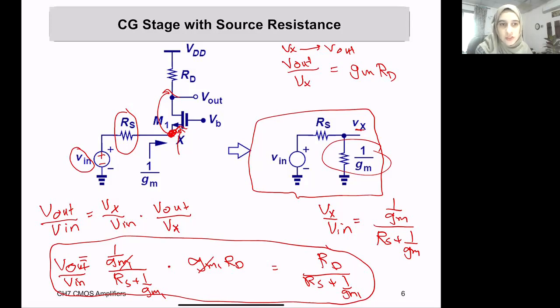I mean, now what has changed? There is an addition of this resistor Rs. So not entirely the Vn is reaching the Vx node. From this node to this node, you have a gain of Gm Rd. But not all of Vn is arriving at this particular node. Oh, okay. Thank you. I got it. Welcome. Yeah, so therefore we need to do it in two stages.